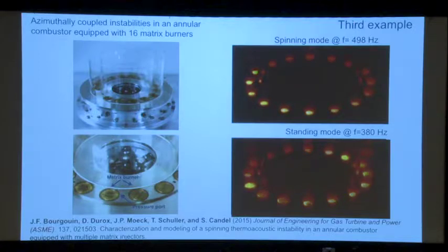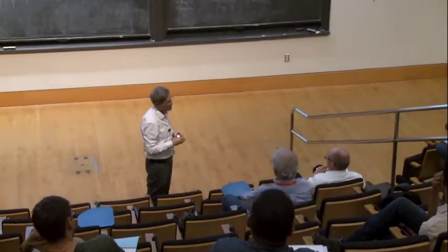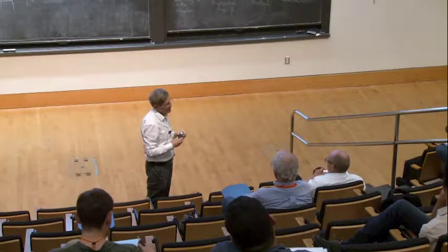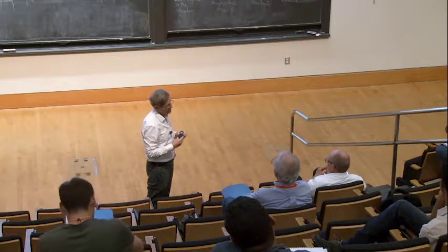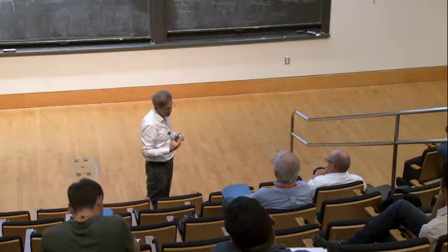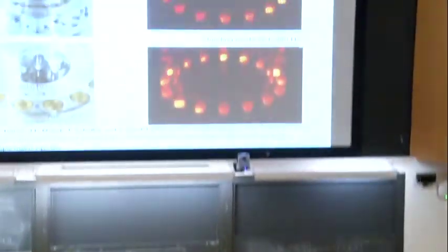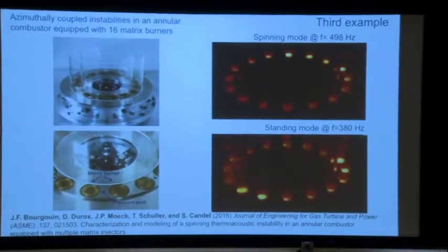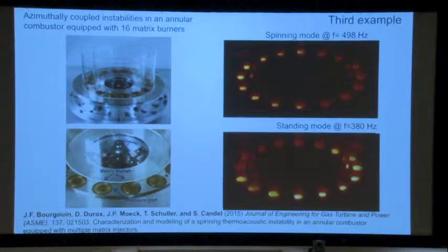Is there any connection between that spinning mode and spinning detonation? No, it has a little bit of the same when you have these spinning things, but the spinning detonation goes near the lean limit. Yes, there is something shared. But here, what is driving this is essentially an acoustic situation, where in detonation you have very strong pressure changes. You don't have that here.